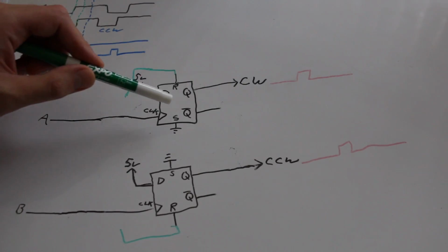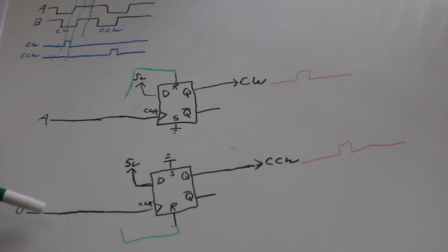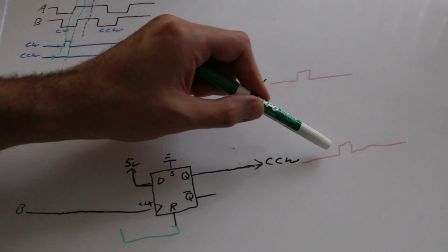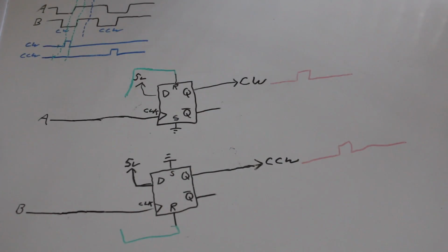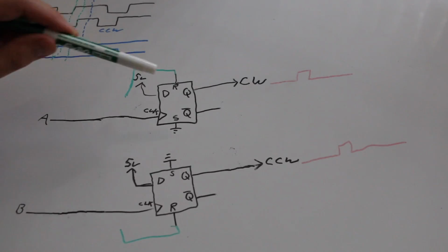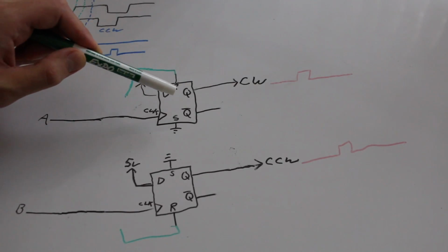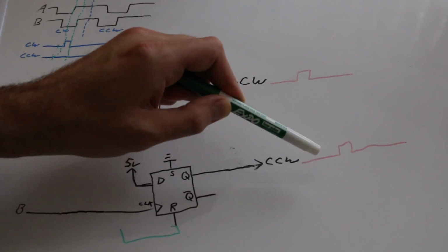And whichever one happens to start generating first, the other one is still going to have a rising edge as well. So as it is, we're going to get both clockwise and counterclockwise, one being slightly delayed from the other. So we need a way to cause a reset after this whole rotation, and we need a way to lock out whichever pulse we don't want.